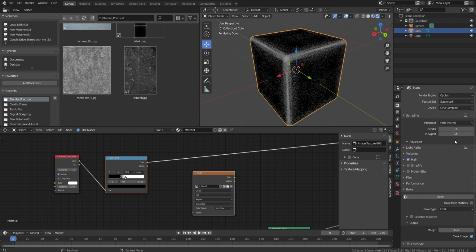I just want to point out, this is a very important one: I don't want my render output to have higher sampling, because then I will lose all these rough informations, which are giving me a randomization over the edges, which is really important. Let me tell you very clearly, this is the key for this baking action. If I pump up the viewport sampling, let it be 16, let me pump up this one.